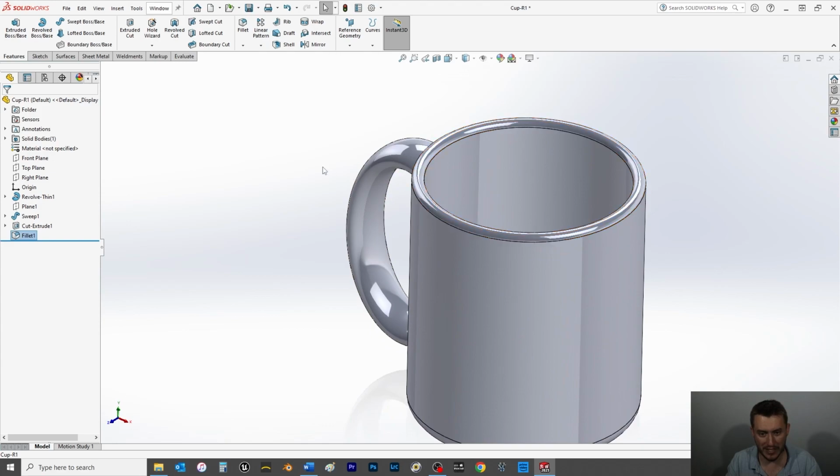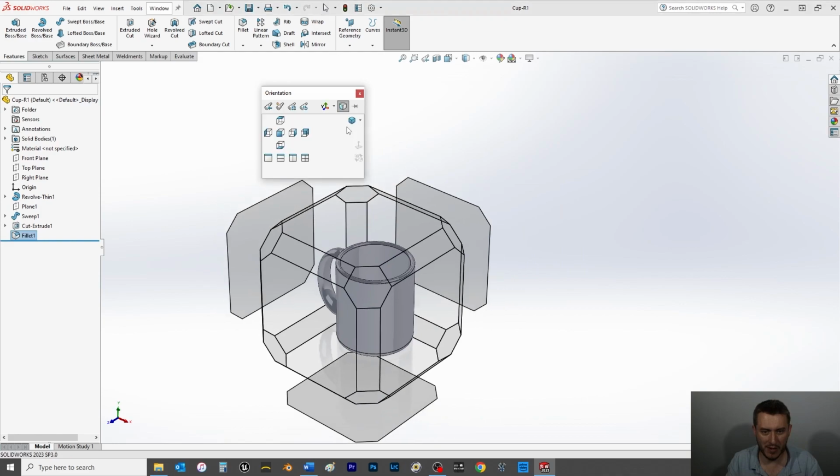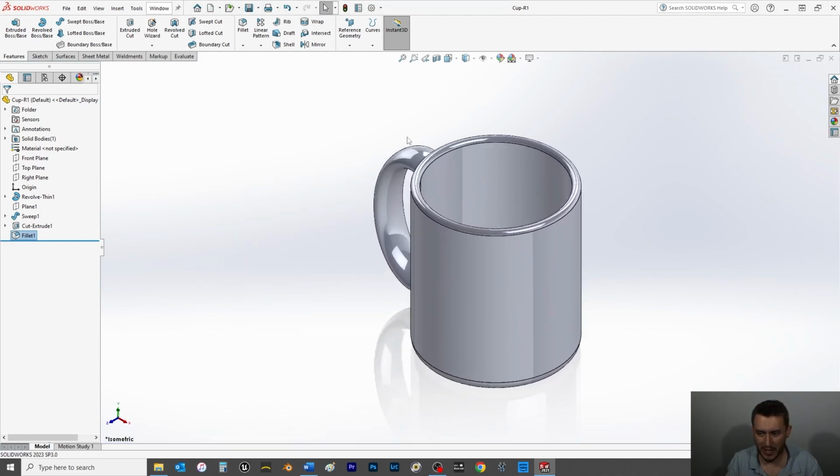rounded radius fillet. Hit Control S, spacebar, bring it isometric, and then we'll now move on to page 259, section 8.10. Alright, home stretch, baby. We're on to section 8.10 on the top of page 259, where we're going to add one more set of fillets. So come up here, choose fillet.